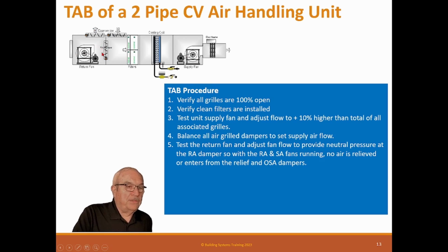Now, normally buildings, no matter how the designer designs it, don't require relief unless they're in economizer mode. So I have seen many designs where the engineer interpreted the building as a balloon. That this building is not going to leak, so we're going to need to relieve air because we're bringing outside air in for the people to breathe, and we need to relieve that air. Well, it doesn't work that way because buildings leak a lot, and normally we leak more than the ventilation requirement. So basically, this fan should not be relieving except in economizer, which we'll talk about in a second. So in normal mode, this should be 0 pressure.